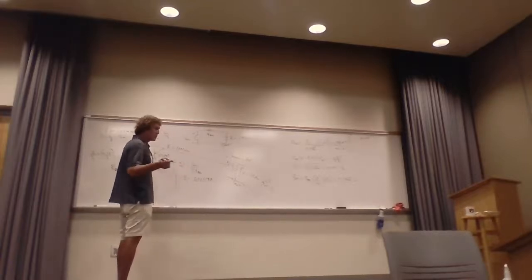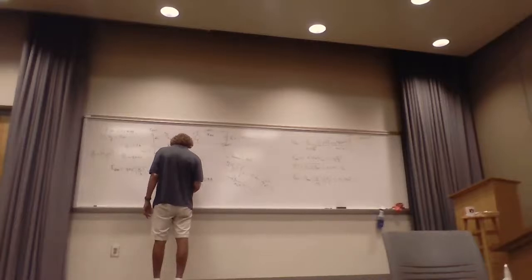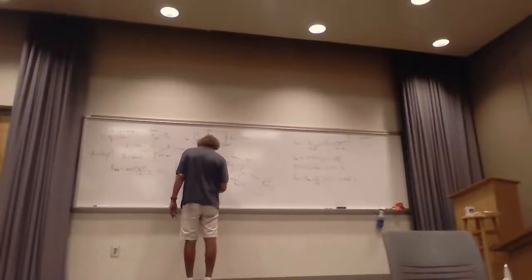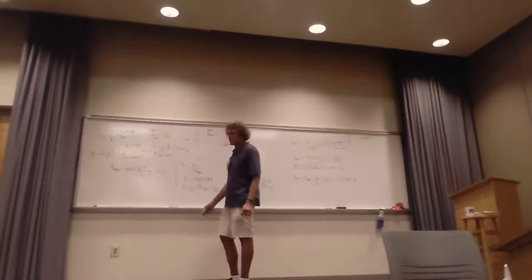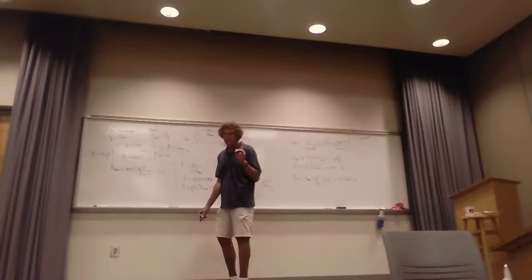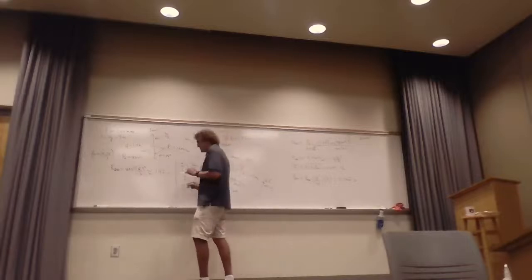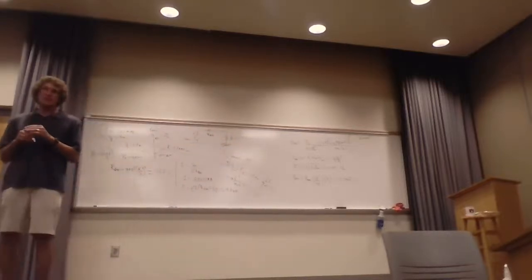milliamps. Yeah, if you want the power at the load, you could go several ways. Power at the load is 1/2 times the magnitude of that I squared times R rad. Or you could just take P received and divide by 2. They'll give you the same answer. And is that 4.6 something? I don't remember exactly. 4.7 micro, microwatts, and I think that's it. Is that right? Okay. Anything else on there? I think that's all, right?